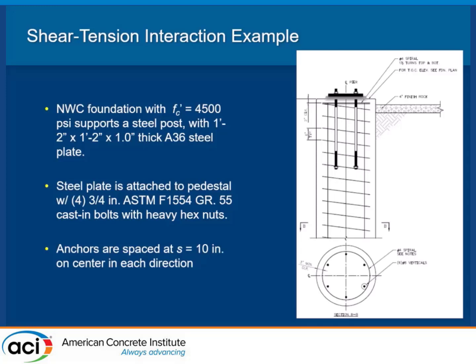Now, I might still have a side face blowout here. Once again, from just observation, of course, I'm experienced at this, I'll tell you that's not going to be an issue. Once you get 2.5, 3 inches away from the side, you'd have to have pretty big loads to get side face blowout. But that's just a feel thing you get over time. So I just had this as an example.